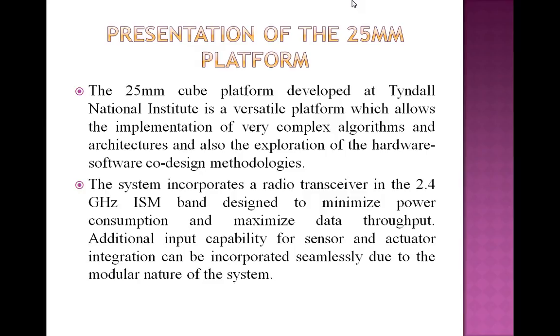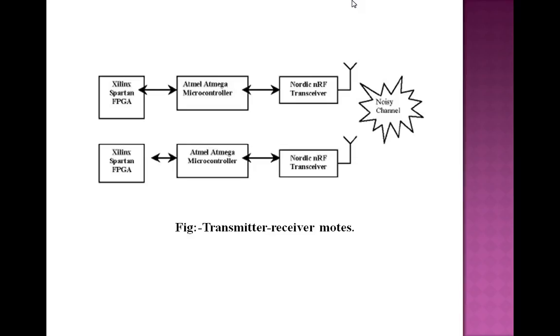The wireless transceiver consists of a fully integrated frequency synthesizer, a power amplifier, a crystal oscillator, and a modulator. Current consumption is very low, and a built-in power down mode makes dynamic power management easily realizable. This feature also helps us to quantify the benefits of the various error control codings used, by keeping the lowest output power for this transceiver and measuring the range of communication.